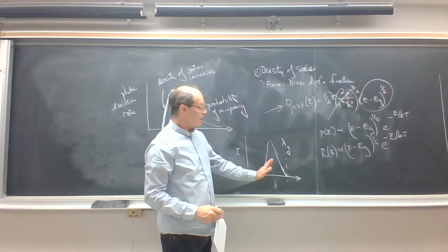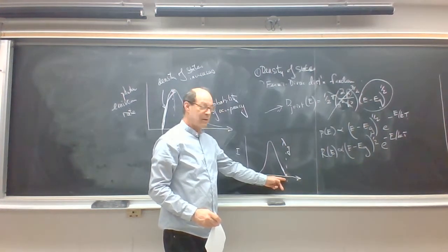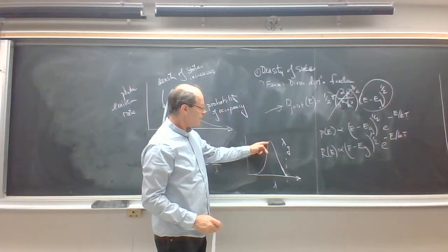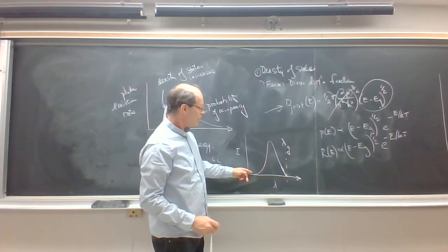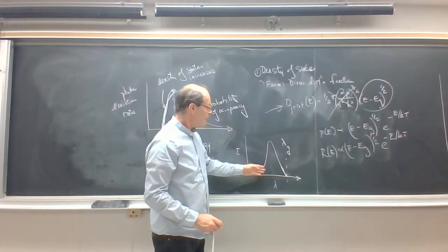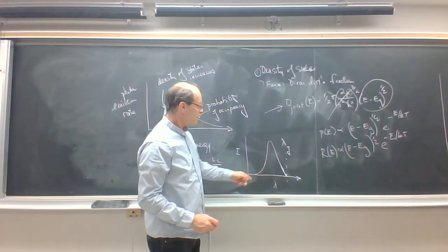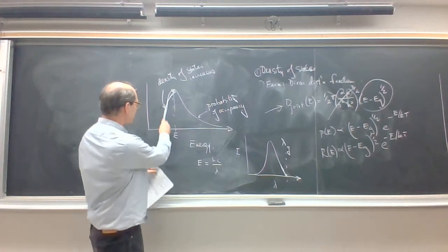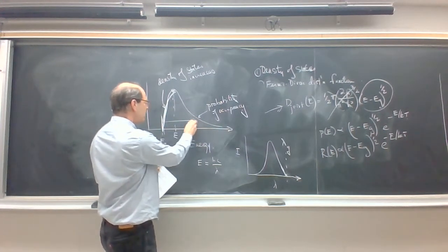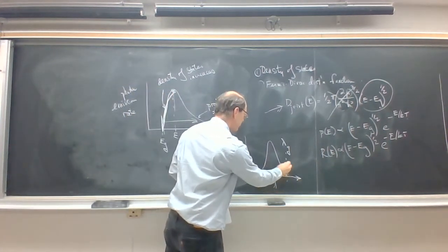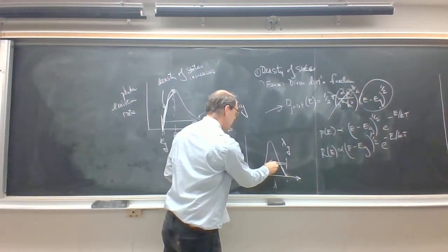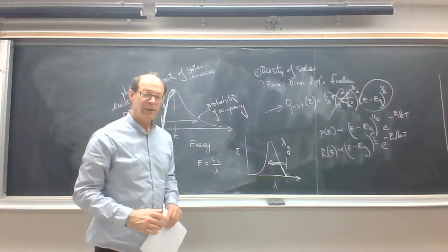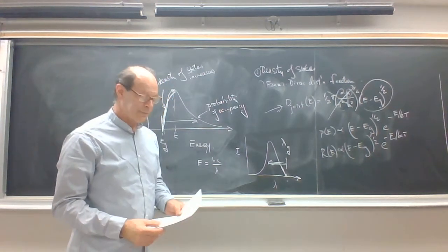So that's the wavelength at the energy gap. And then the wavelengths will get shorter and they'll die away. So as the wavelengths get smaller, the photon energy gets bigger. So you're starting there at the band edge and traveling to the right. In the case of wavelengths, you start on the right and you're traveling to the left as you exceed the band gap of the semiconductor.